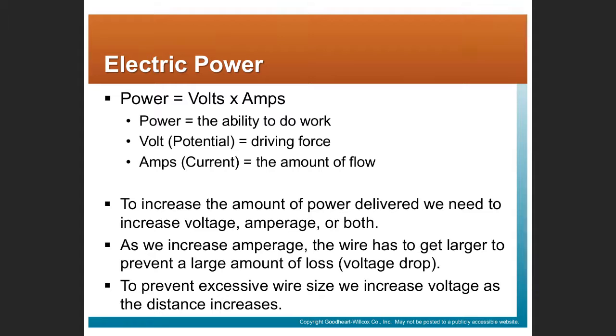All those we're using electricity to do useful work, right? The power is generally speaking the product of volts multiplying amps. Amps is current, is the amount of electrons trying to get through the wire. So we want to do more work. If we want more power, then we have to increase the voltage or the amperage, or both, right? But when we increase the amperage, we have to watch voltage drop, right? How the voltage changes from one end of the wire to the other.